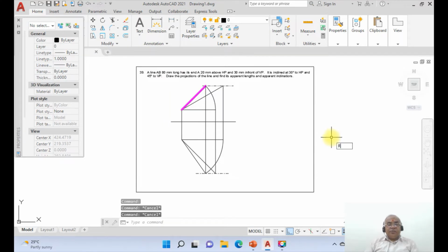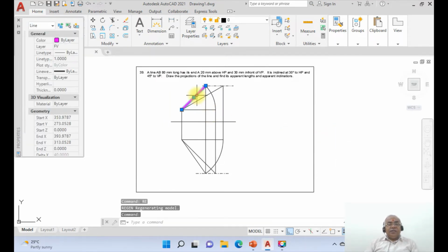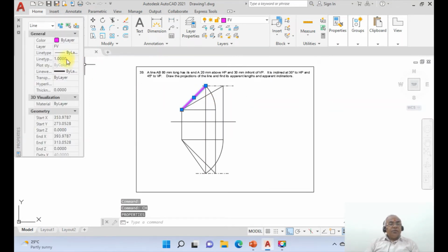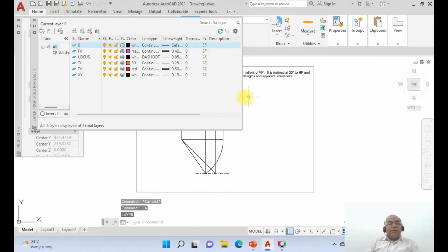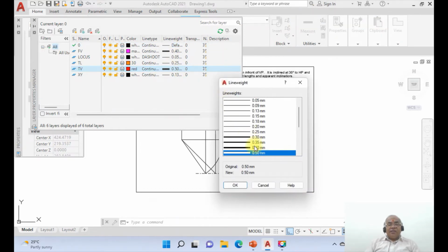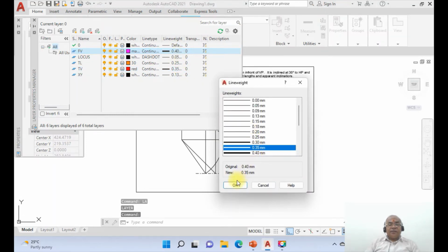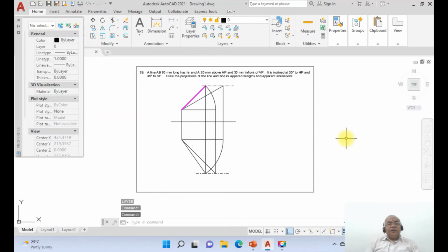So therefore you just go to region red, you select this and go to front view. Okay, go to line weight, so region. So you just go to CH, go to layer, you select this layer as front view. Okay, now if you go to the layer and you see the front view should be of 0.4, and then here also I will take it 0.35. Okay, you just click on this, and here also you just take 0.35 because it's too heavy for the... now it is a bit okay now.